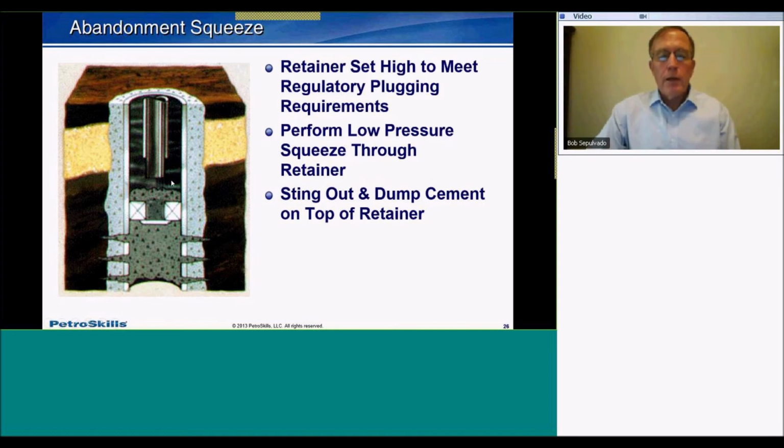Depending on the regulatory agency, there are other guidelines on what to do further up the hole for other formations, and setting plugs at the bottom of the surface casing may be something that is added on there too. So just reach out to your local regulatory agency, work with them, find out what the exact guidelines are for successfully abandoning a well.